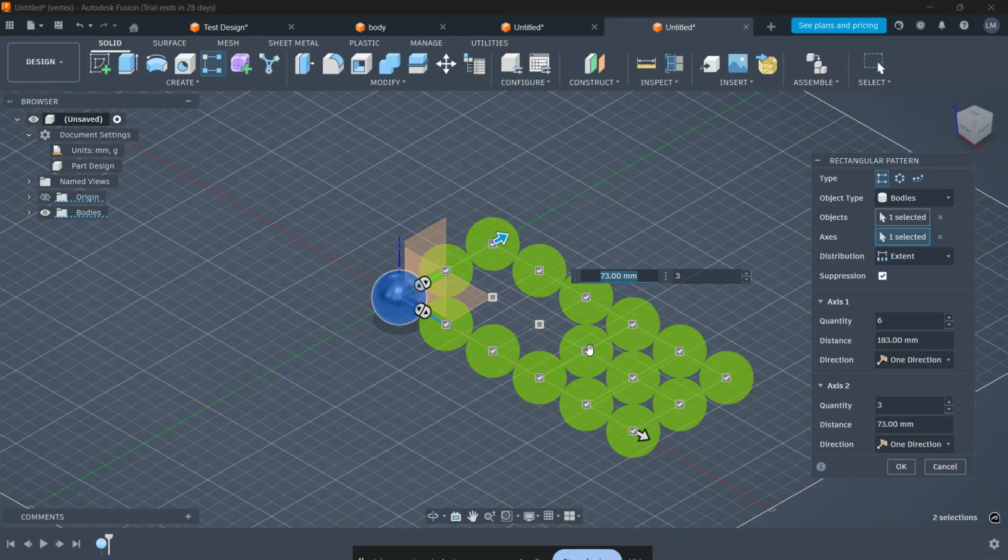Once you are satisfied with how the preview looks, take one last look at your settings in the dialog box. Ensure your alignment is set to identical or adjusted based on your preference for how the objects orient themselves along the path. When everything looks perfect, go ahead and click the OK button. Fusion 360 will now process the command and generate the geometry.